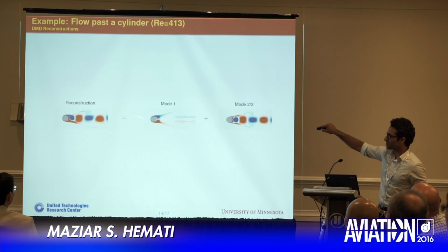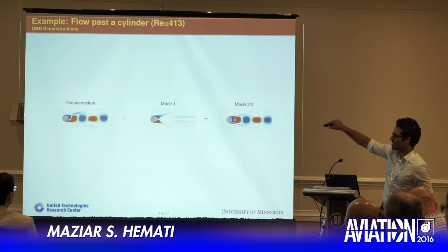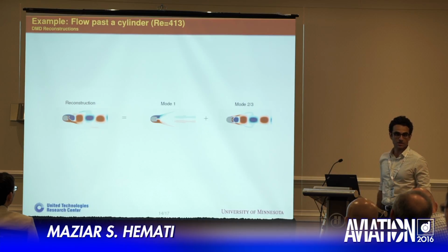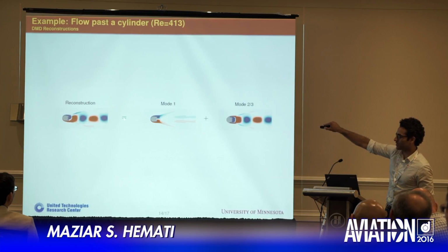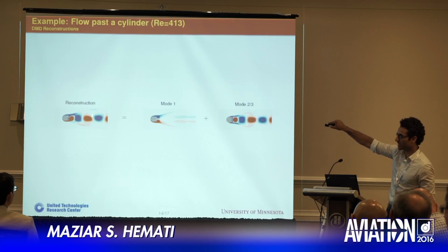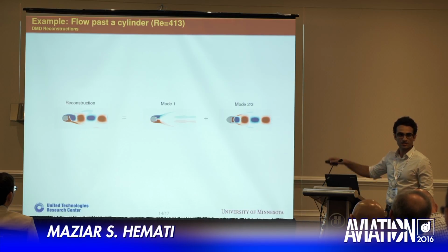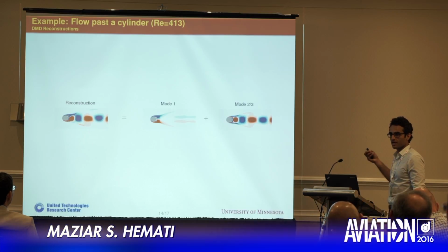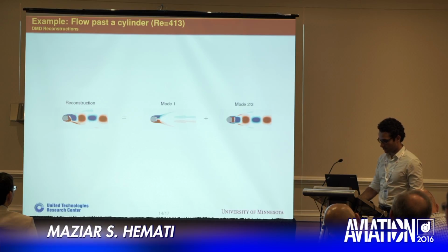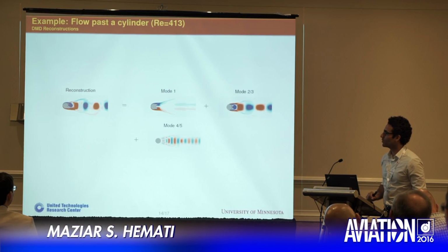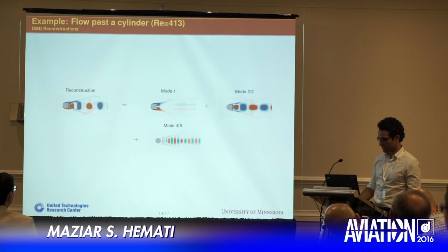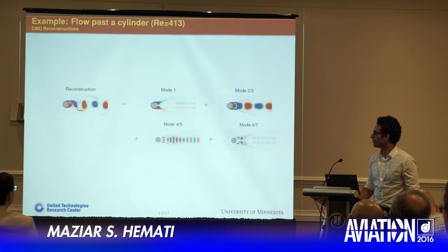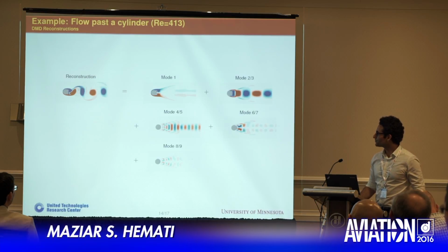If I can reconstruct it with just these two modes, so I have my constant mode plus the fundamental frequency mode, if I do that, this is my cartoon of a 2S wake right here. And we see I capture the top-down asymmetry. I also capture a lot of the concentrations of vorticity that are just emanating down. Okay, but I can also refine that picture by adding more and more modes. These are being added sequentially in order of max amplitude.